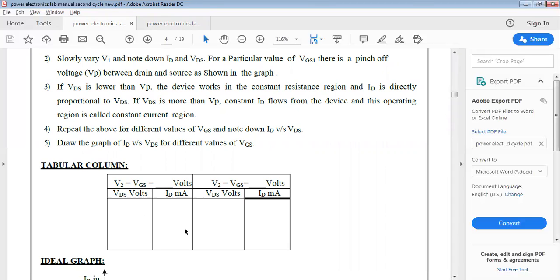We know that whenever the MOSFET is in on condition, ideally the voltage across the drain to source must be zero. Since it is a non-ideal device, we can expect some voltage to be present across the drain to source. And as we are increasing the supply voltage, we are expecting the voltage across the drain to source to be constant, if not zero, or even if it varies very marginally, till a particular value of the supply voltage.